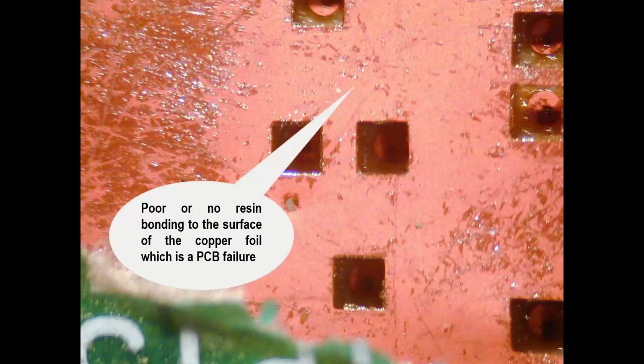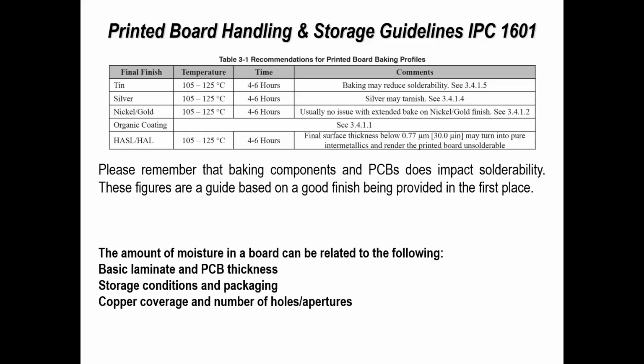So what you're looking at is the copper. The holes, the square holes, are where the plated through hole will have gone through. And what's happened is it's delaminated, separated. But it's clear to me that there is no bonding of the epoxy to that copper. You can see little areas, there's a little bit of glue there, but really there's a problem there. So that board was always prone to issues. It's not just me, the assembly engineer, making a mess of the soldering operation. Clearly there was a problem to start off with. So again, it's understanding the board technology, and you should be able to overcome that.